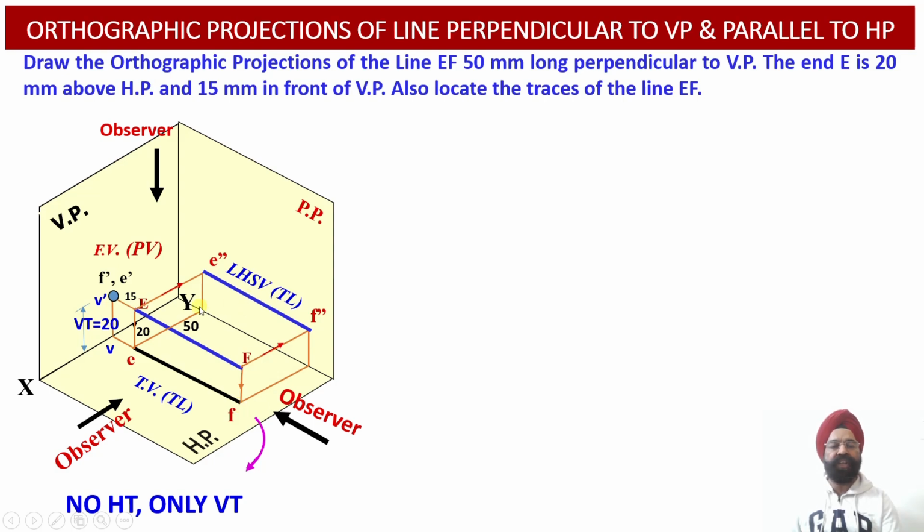So the side view projection and the top view projection are correlated with each other. Similarly, we have to establish the relationship between the left hand side projection obtained on the profile plane and the front view projection. So please check. Again, two construction lines we are required to draw over here. One through the extension of E double dash and F double dash, and another one parallel to the XY reference line, drawn through the points F dash and E dash.